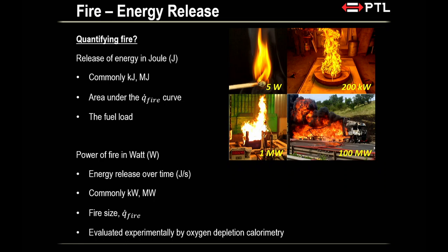And we have a term for the energy release. That is the fuel load. So you will hear me mention fuel load in our subsequent discussion as well. Now that's the area underneath the curve, but the curve itself is the power of the fire. Okay, it is in watts. It's joules per second, or more commonly, kilowatts or megawatts. That's the sort of fire size we deal with.